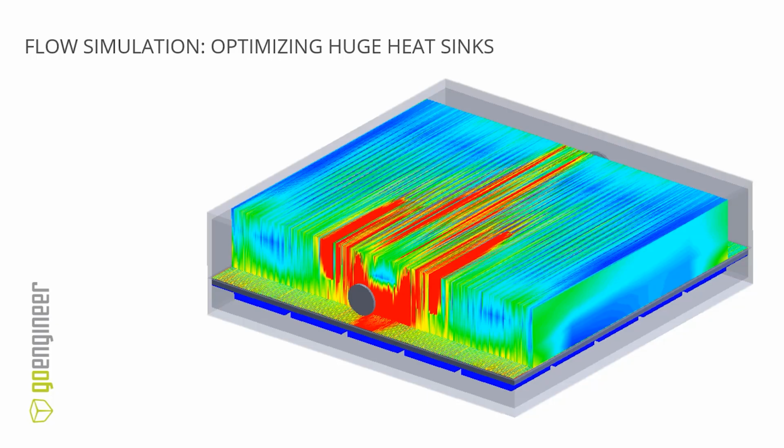I'm here to talk about optimizing large heat sinks, largely focused on the idea of solve time. So what can I do with the mesh to make this solvable on a single computer? What can I do with analysis methods to make this more efficient to solve? This is more focused on meshing and methodology rather than just some of the optimization tools that are built in.